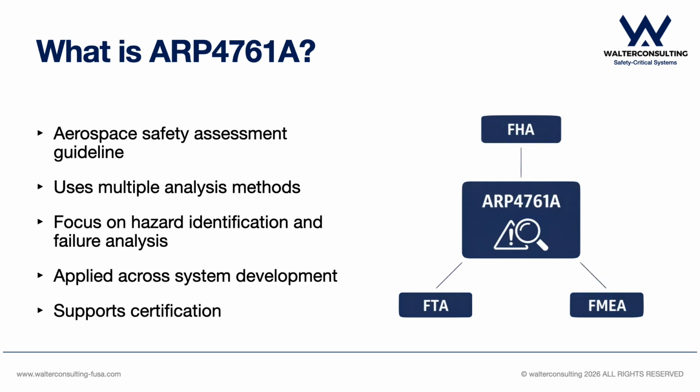Let's briefly recap ARP4761A. It is a guideline for safety assessment in aerospace. It uses multiple analysis methods, such as FHA, FTA, and FMEA. The focus is on identifying hazards and analyzing failures. These methods are applied across the system lifecycle, and they support both design decisions and certification activities.